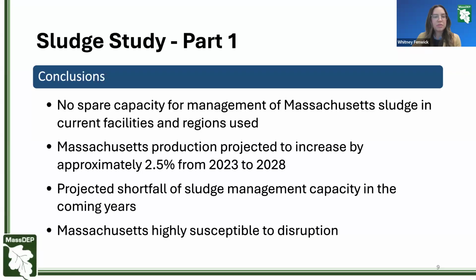The goal of Part 2 was to consider the future options and associated costs of managing wastewater sludge that contains PFAS. Part 2 includes an evaluation of how legislative and policy decisions for regulating PFAS could affect sludge disposal capacity, the contributions of PFAS into POTWs due to indirect discharges, PFAS reduction and destruction technologies, a series of sludge disposal scenarios and analysis, and options for the state and POTWs to consider moving forward.